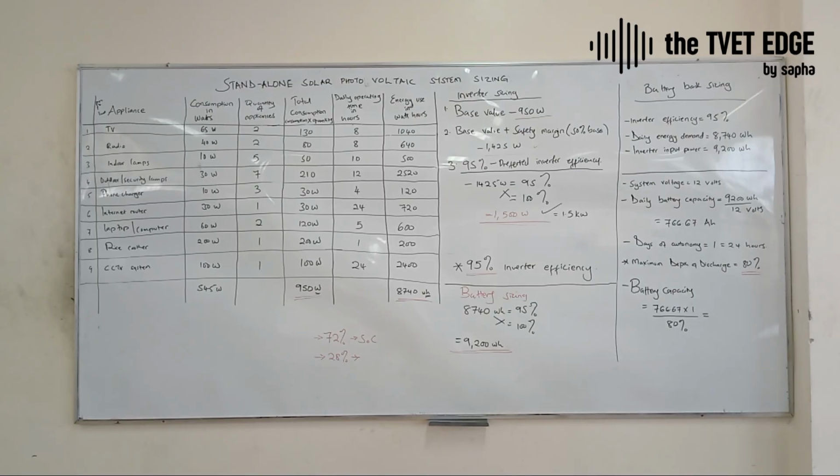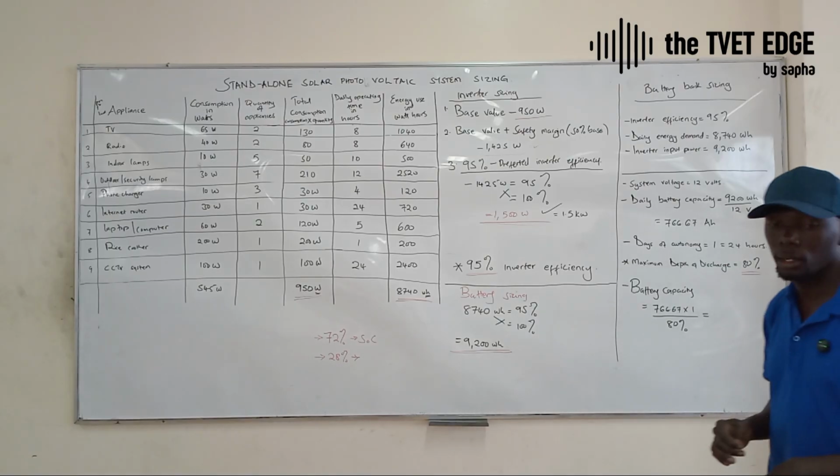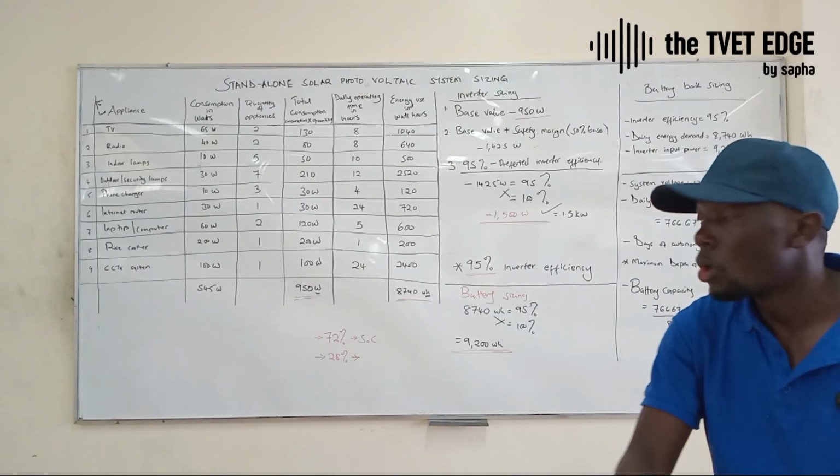The state of charge is what is in the battery, whatever is now remaining for you to take out. The depth of discharge is the maximum that you can take out. So if it's at 100 and the maximum that you can take out is 80%, that means that the depth of discharge is equivalent to 80%. I hope that is well understood.